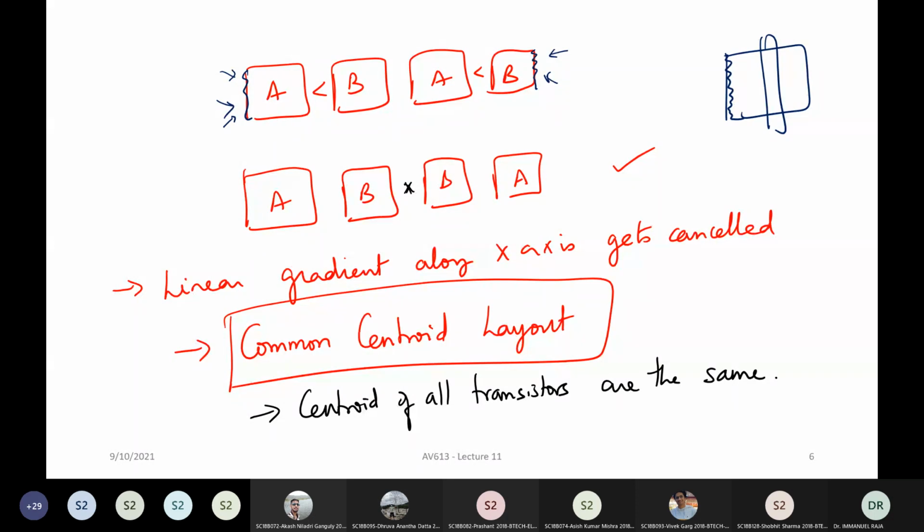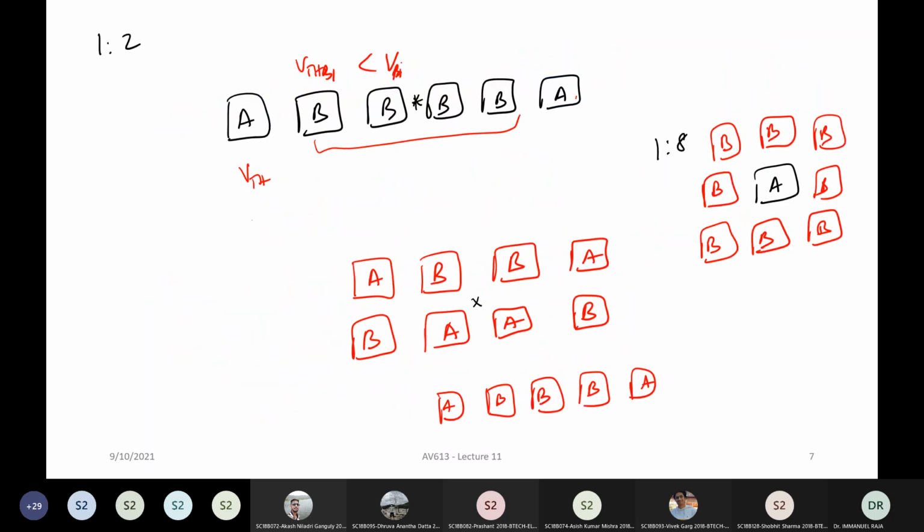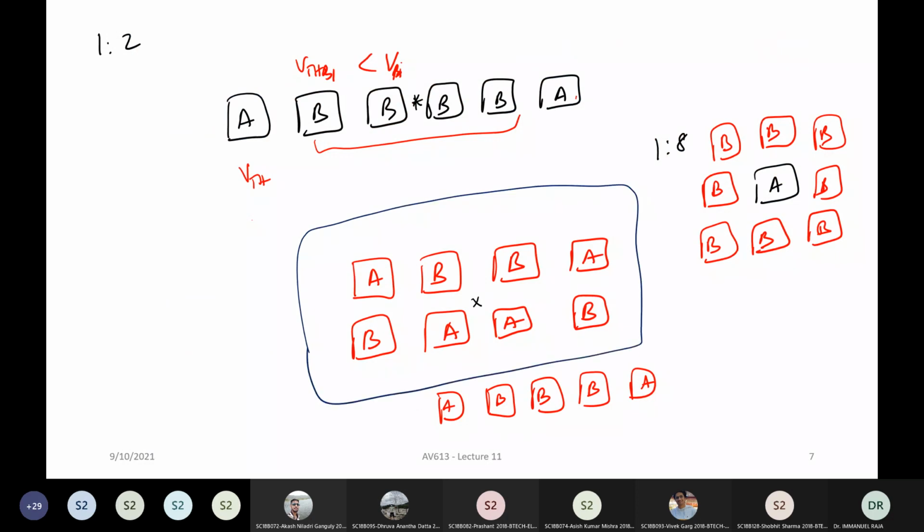Because of that, they will put what is called dummy devices. If you look at all these current mirror layouts, especially sensitive analog layouts, they will put dummy devices. In fact, if you have a two-dimensional layout like that, you will have dummies all around. With the polishing and other things coming from both directions, the dummy devices have the gate, source and drain all connected to ground.